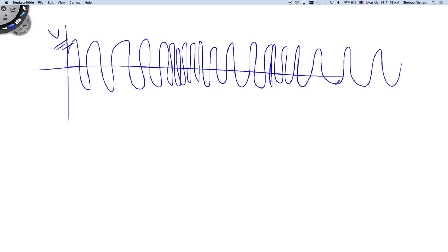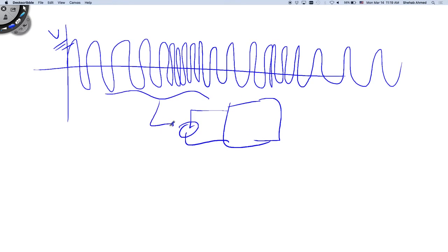So you will take this signal and pass it through an electrical circuit, a box here. This voltage is this signal that you have here. You pass it through a box, and this box will give you 103.4 or 100.3, whatever frequency you want to listen to. How does it do that? It will have to have a frequency response that will eliminate everything but this frequency.